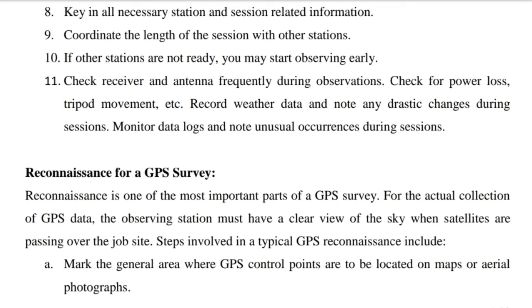11. Check the receiver and antenna frequently during observations. Check for power loss, tripod movement, etc. Record weather data and note any drastic changes during sessions. Monitor data logs and note any unusual occurrence during sessions.